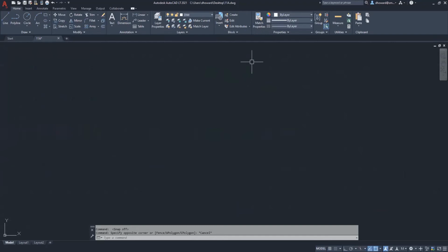So the very first line I'm gonna draw is a construction line. So I'm in my construction layer, and I'm gonna XL enter, and just kind of randomly place it. And I wanna make sure it's vertical. So I'm going to take advantage of this ortho snap down here. See this one right here, this ortho mode? By the way, that's F8.